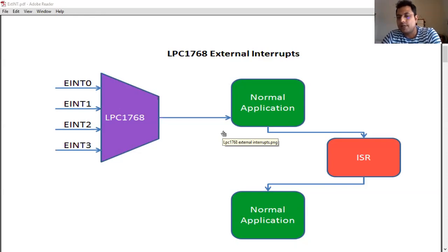And now we have different types of interrupts. These interrupts we are handling are hardware interrupts. Some software interrupts are also there, as in every language, you know the concept of interrupt handling. Those are called software interrupts. Some are nested interrupts. What is the meaning of the nested vectored interrupt controller, why is the word nested there? Nested means when you are already in an interrupt, within the interrupt another interrupt is possible.